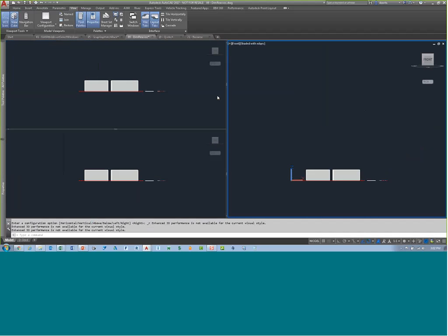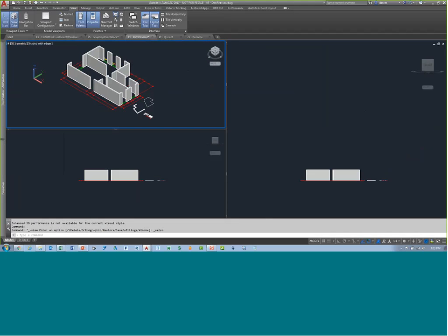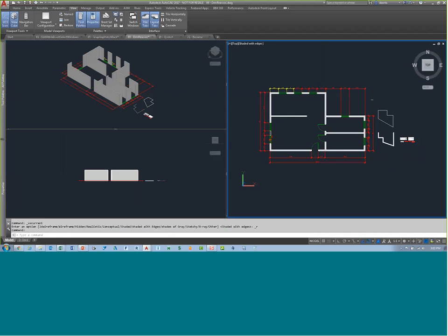But doing it this way doesn't afford the ability for you to make adjustments to how the display of each one is supposed to look and show the data prior to making it. So you'll just have to go to each one and manually adjust it to whatever view and position you want, which you can do with the view cube, or you can do with the text here. And you can also adjust the visual style by using the text here as well. For example, this could be the top, this could be the front, and this could be the isometric view.